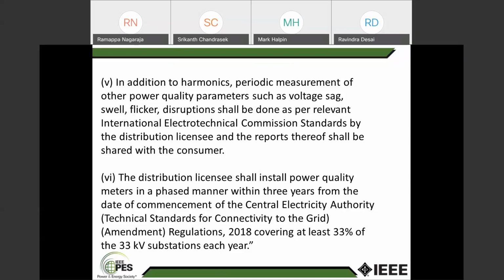For example, if an end user is known to not produce voltage fluctuations and flicker, then the utility company is not going to pay attention to the flicker indices that might come from a power quality monitor. They're there, but that probably won't be included in the contract for service for that user. So there's a little bit of variation in what indices and what limits are given to what customers in terms of the different power quality phenomena.